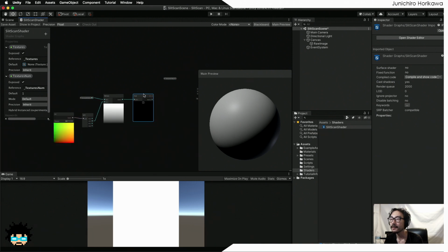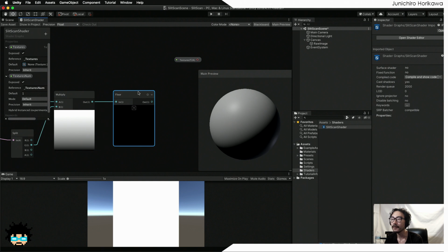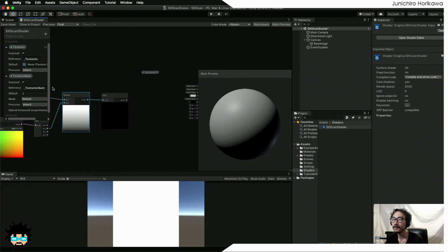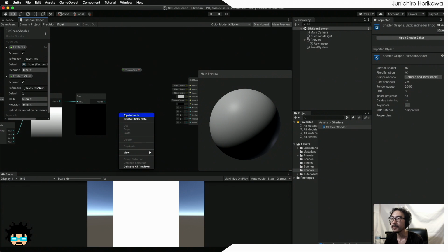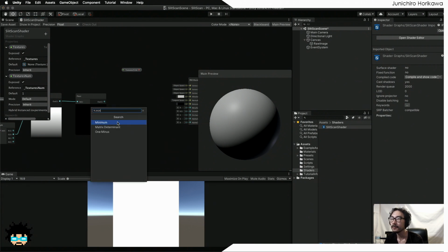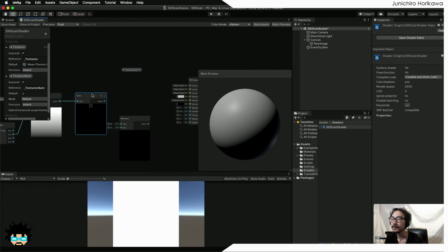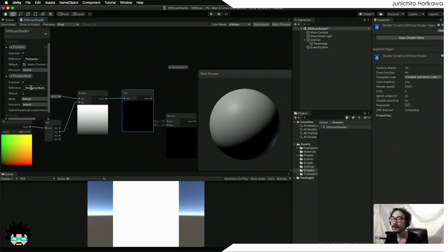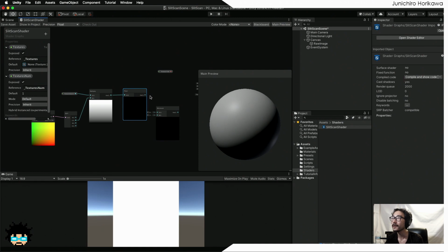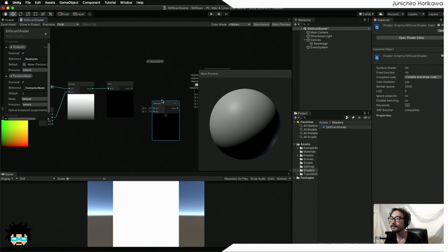Now there is a chance that you are left with 0 or 1 in this case, and if there's only one texture, you don't want the value 1. So we are going to create another node. If the value is equal to the texture num, then we are going to subtract it by 1 using a minimum node.